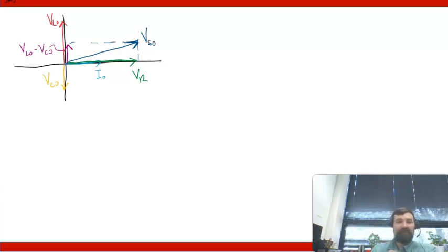Now, there is going to be some angle phi between the voltage across the resistor and the voltage across the source, assuming, of course, that we have a capacitor and an inductor and that our omega is non-resonant. When it's resonant, then VL naught and VC naught actually will add to 0, as it turns out. So you can figure out the resonant condition just from that.